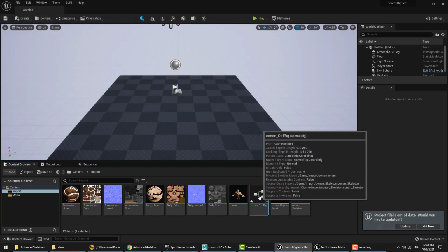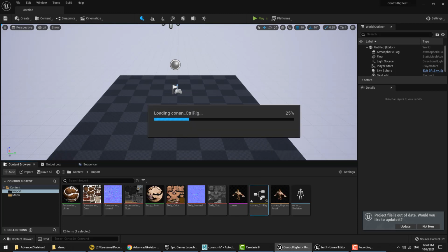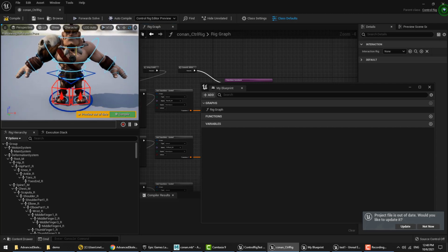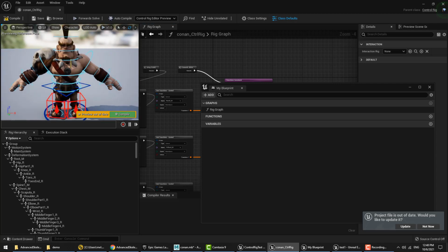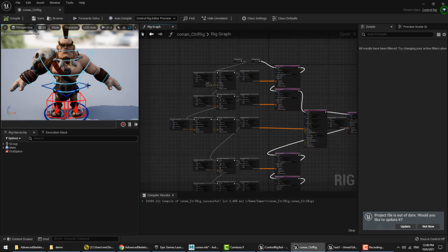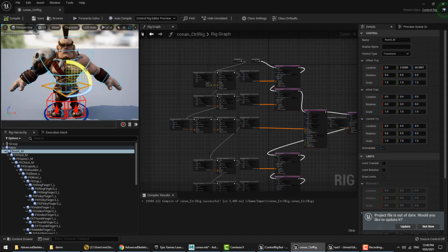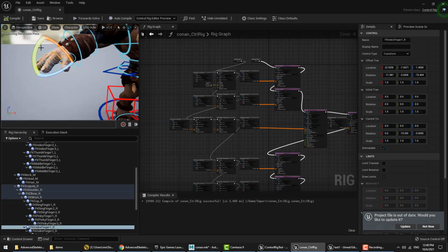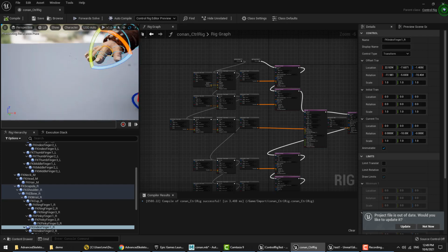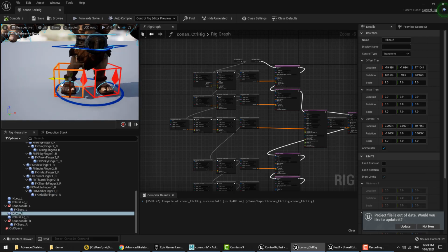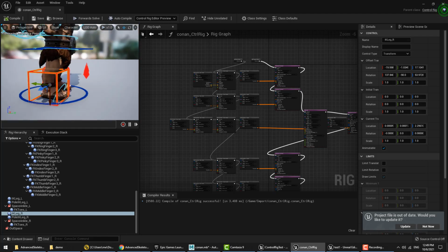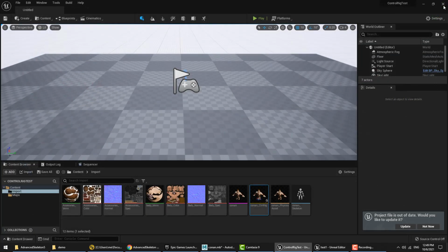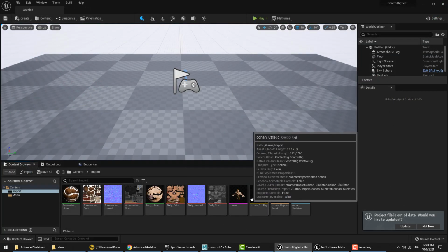That should run within a few seconds since we turned off auto compile, and we can now open the control rig node. And we have a control rig that very much resembles the Advanced Skeleton rig. We can go ahead and test some of the controllers. We can see that we have FK on all of the arms as well as on the fingers. And we have IK legs that we can move around, and they have these pole vector objects where the knee is pointing.